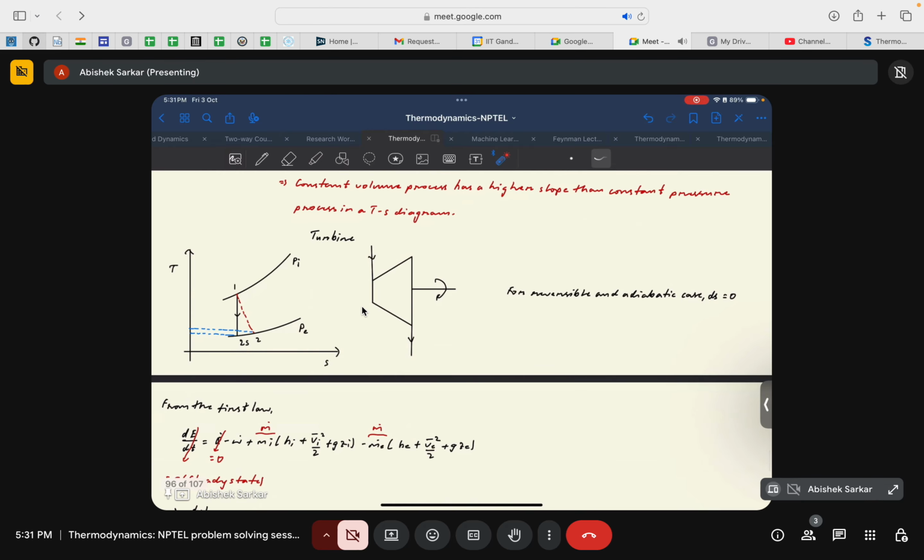In the case of turbines, we saw that the primary task of a turbine is to produce work by expanding the working fluid. By expanding, I mean that it causes the pressure to go down. When we studied the Rankine cycle, we saw that when the working fluid passes through the turbine, its pressure goes down and it expands, and it is this expansion that produces the net work.